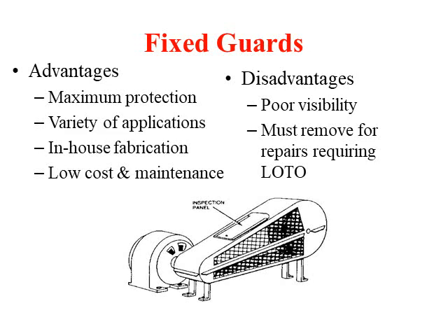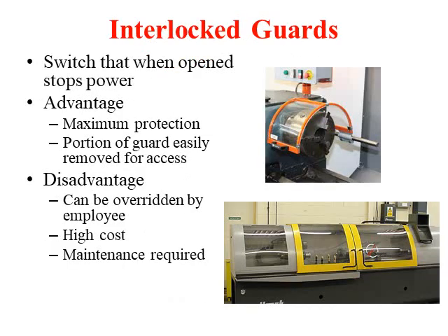But there are certain disadvantages. Visibility is poor because it is almost fully covered. And whenever there is a repair, the whole guard has to be removed. So removing and fixing takes time. That was regarding fixed guarding.